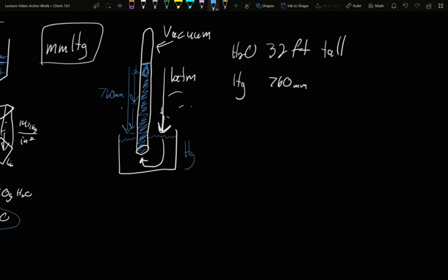It's literally measuring the height mercury would go up the tube. Because that is the height where the weight of mercury pressing down on the area of the tube is equal to the weight of the atmosphere pressing down on a similar area of the pool of mercury at the bottom of the bowl. Key to pressure measurements in this case with these little devices are the opposing forces. How much pressure is in each direction? From multiple sources, just add them together. Total pressure from the inside, total pressure from the outside.